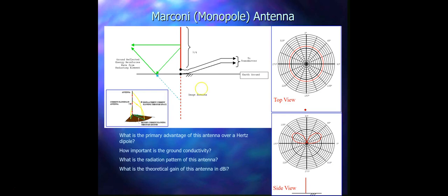This type of antenna is extremely dependent upon the conductivity of the earth, because the earth acts as a mirror, and we need to increase the conductivity of the earth. As I told you, the earth conductivity can be improved by an artificial low-loss ground, or we can also use a radial system. A radial system improves the conductivity of the earth, and it should be laid out in a pattern that follows the ground current running radially out from the feed point of the antenna.